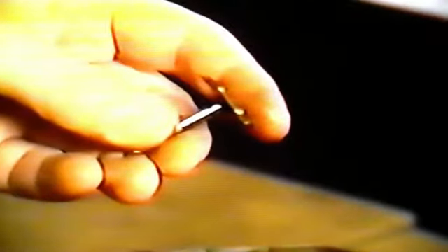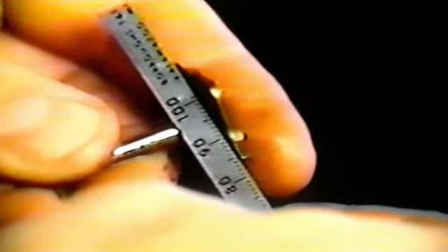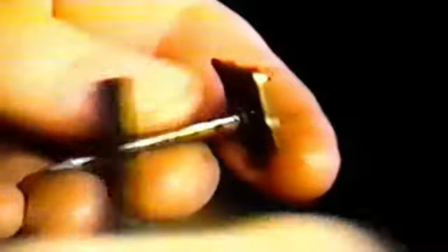The first thing you want to look at in the bowl is the mixture control solenoid paddle. Even though it was operating correctly in the earlier test, you still need to do a visual inspection by pulling out the paddle and making sure both arms are even. It's also a good idea to take a small straight edge and hold it across the arms to make sure they're parallel. A bent arm will result in uneven positioning of the metering rods.